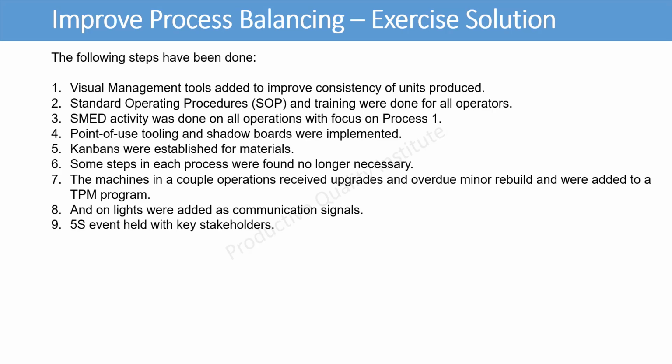The following steps have been done. Visual management tools added to improve consistency of units produced. Standard operating procedures, SOP, and training were done for all operators. SMED activity was done on all operations, with focus on Process 1. Point-of-use tooling and shadow boards were implemented.